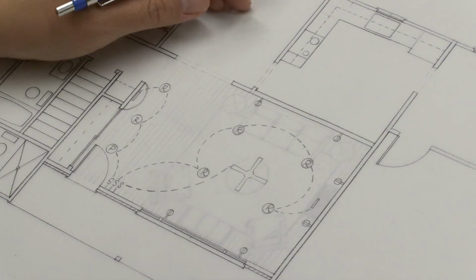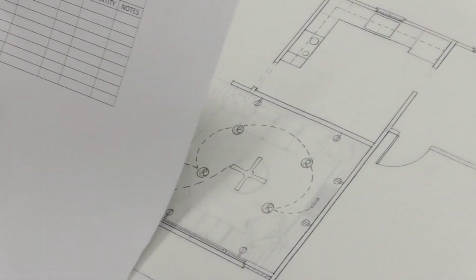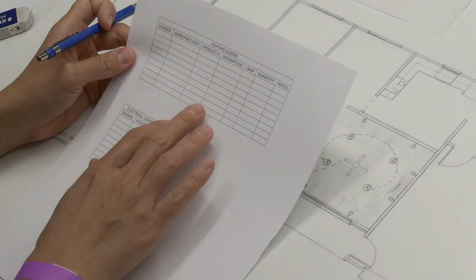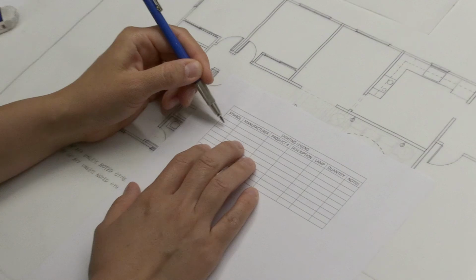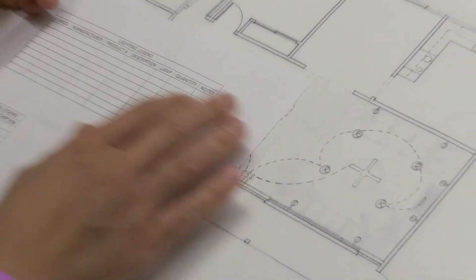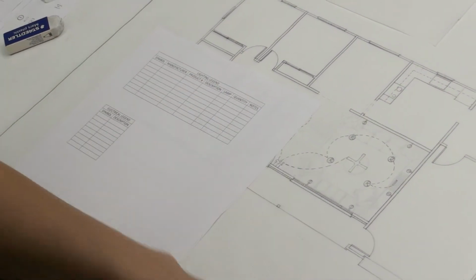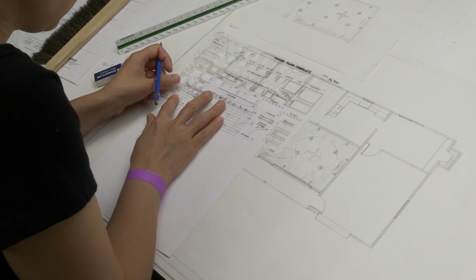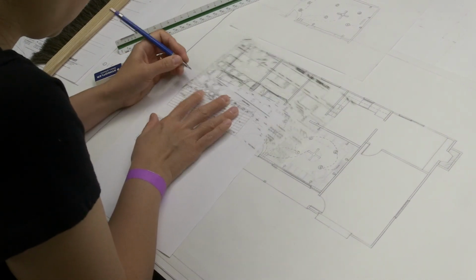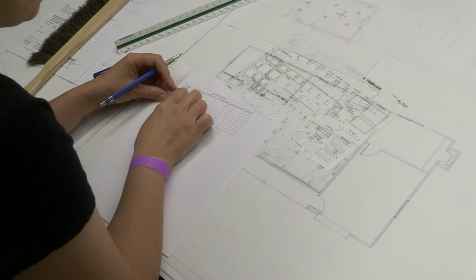And also one last thing that I wanted to show you guys is the schedule lighting legend. So you would have to create a lighting legend where you would have to draw the symbol of your lighting fixture. So if it is recessed, you're gonna draw a circle just as you have it here, exact same. So you're gonna draw a circle here and put the letter R in here. So this is the symbol for your lighting fixture.